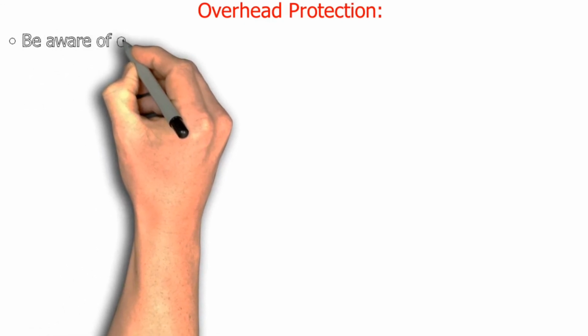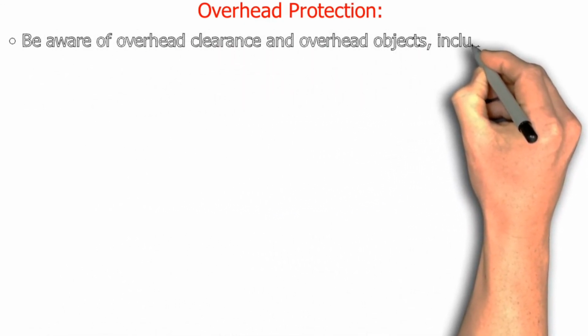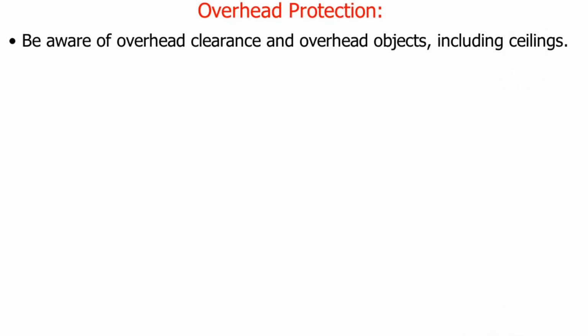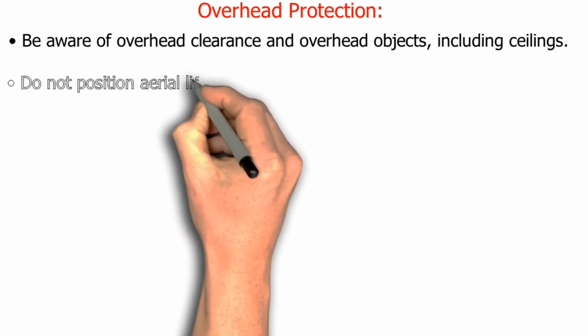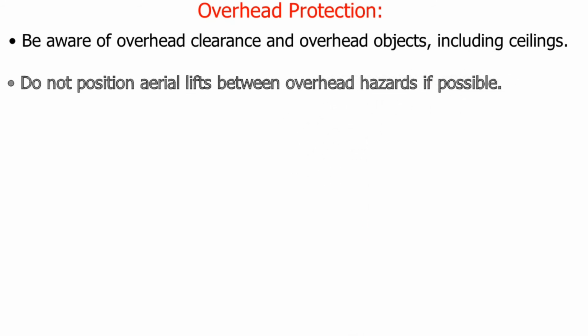Overhead protection. Be aware of overhead clearance and overhead objects, including ceilings. Do not position aerial lifts between overhead hazards if possible.